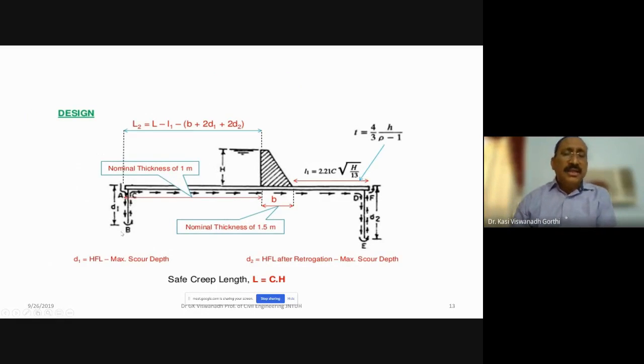So when you are taking the path of flow of water, the flow of water is taking place along this arrow, taking a turn, moving up and moving in this direction. So for the pile AB, you have two faces. One face is the outer face, where the vertical direction flow of water is starting. Then after taking a turn, it is moving inside. So this is the outer face of the pile, and this is the inner face of the pile.